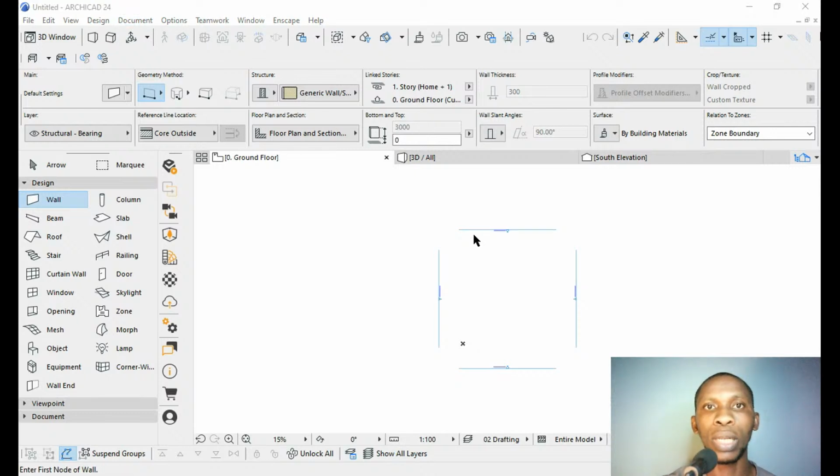We click on it and select scale. One is to 100. You make sure that it's on scale, one is to 100. If you are going to print out a project, you check out the paper size and then use your scale rule to measure the paper size and see if the scale you are using on your Archicad will enable you to print out the document. Are we together? Right. Now I'll click on OK because it is okay.